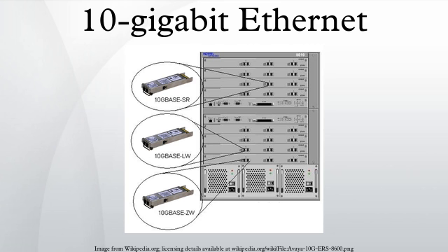The 802.3 standard also references ISO/IEC 11801, which specifies optical MMF fiber types OM1, OM2, OM3 and OM4. OM1 has a 62.5 micrometer core while the others have a 50 micrometer core. At 850 nm the minimum modal bandwidth of OM1 is 200 MHz·km, of OM2 500 MHz·km, of OM3 2000 MHz·km and of OM4 4700 MHz·km.